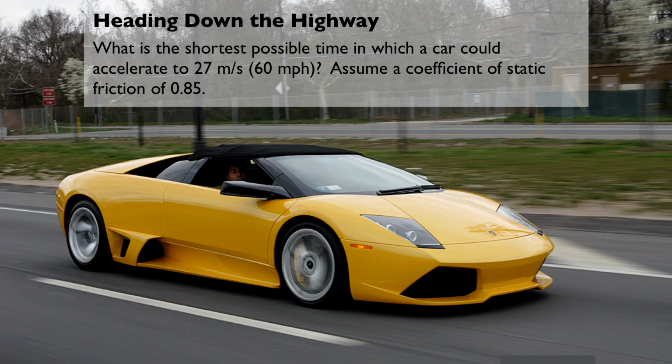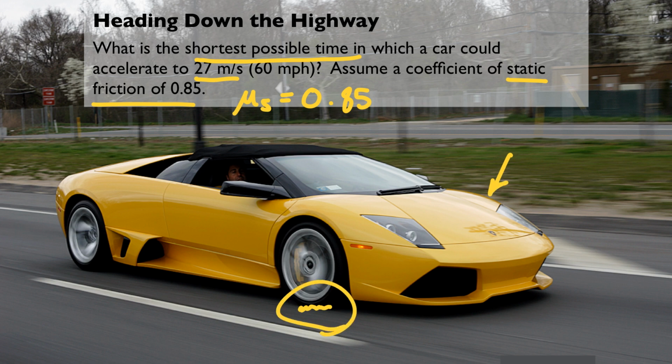Now let's take a look at the type of problem we're going to be solving. This question asks: what is the shortest possible time in which a car could accelerate to 27 meters per second if we're assuming a coefficient of static friction of 0.85, and that's static friction between the tires and the road surface. I know the previous slide said it was more like 1, but this is under real-world conditions, where the coefficient of friction between a road surface and tires might be about 0.85. That's a reasonable value. We'll see that ultimately what limits the acceleration of a car isn't the engine under the hood. It's where the rubber meets the road.